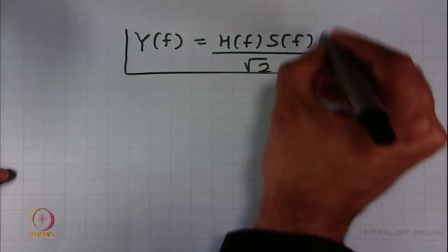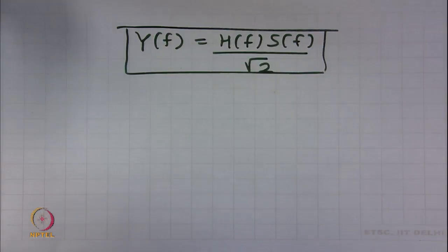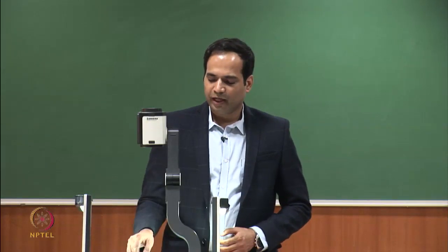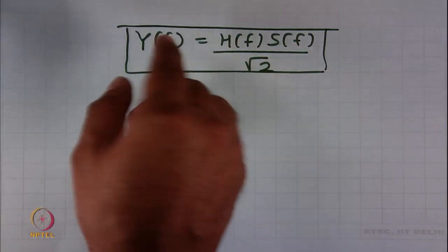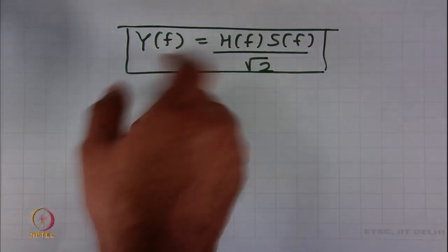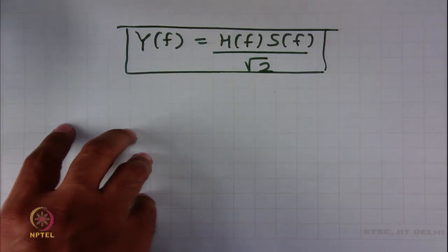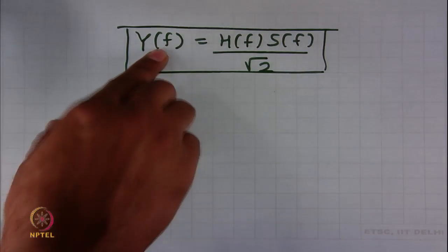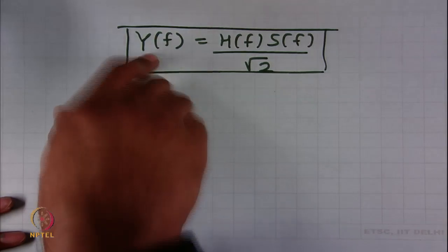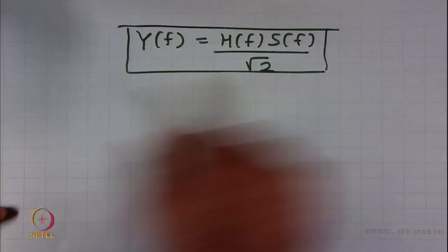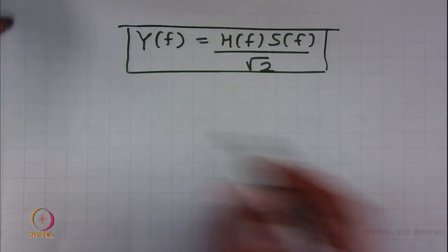What we learn from this is, if you have two baseband signals, you can do this operation in the baseband domain. What you end up with is the spectrum of the resultant baseband signal. So, Y(f) is the spectrum of the baseband signal of y_p(t). Okay. Let us see more about this.